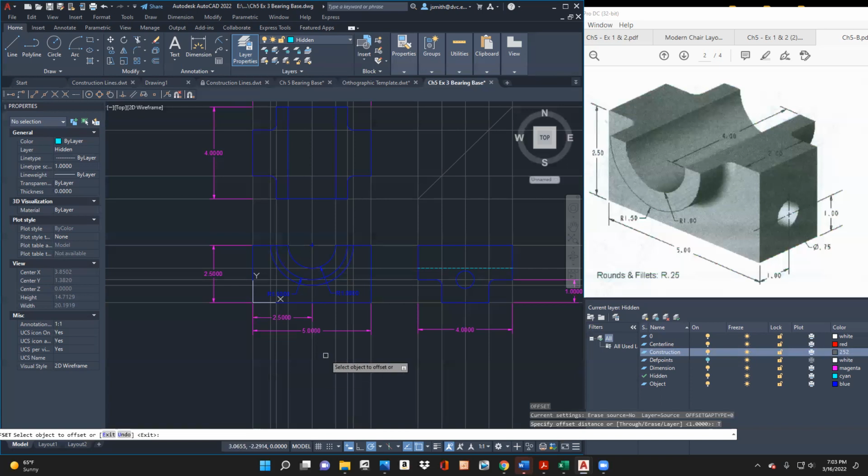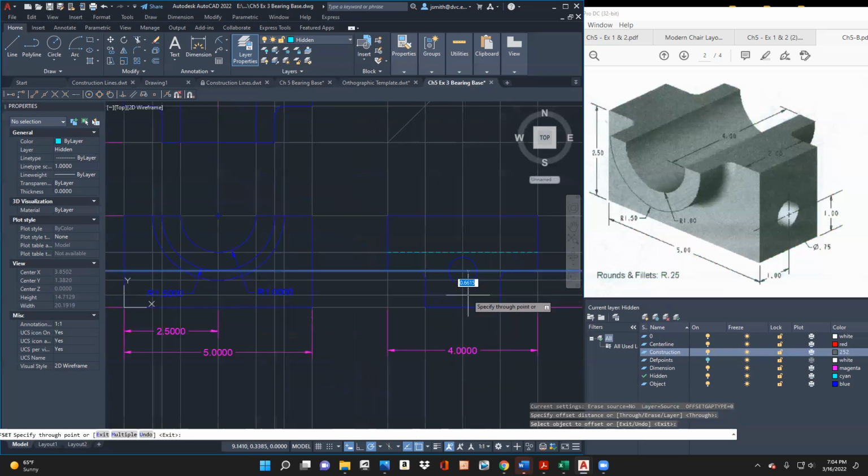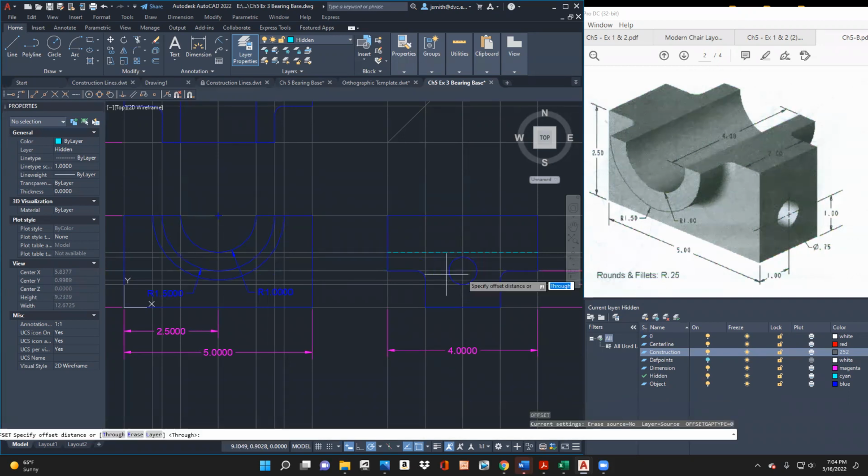The through, the object would be here. The distance is, I could snap it, but let's just be sure. 0.75. Am I doing my math right? Well, let's just go like this then. Let's go enter. There's the object. It's coming down at half of, so it's going to be 3/8 or 0.375. Enter, do the same thing and snap it there, 0.375. So the reason why I did that, then I'm going to have to do the same thing here in the top view.